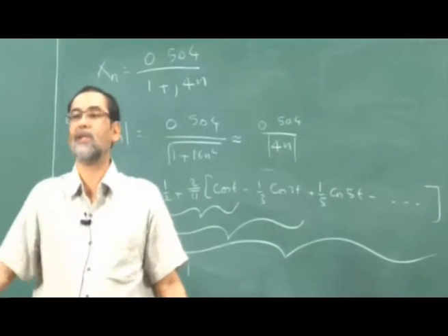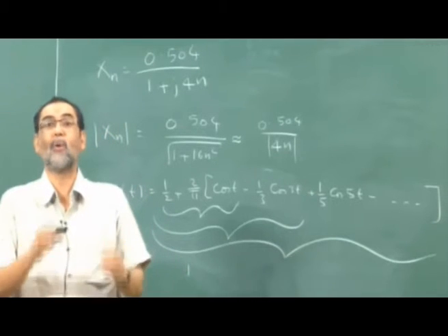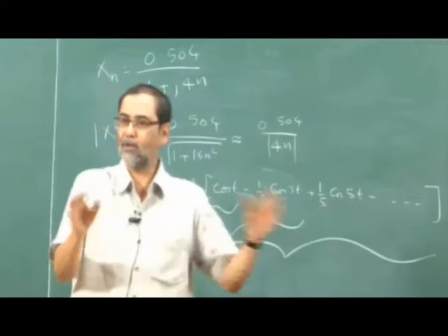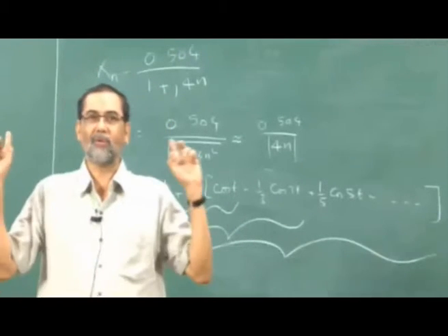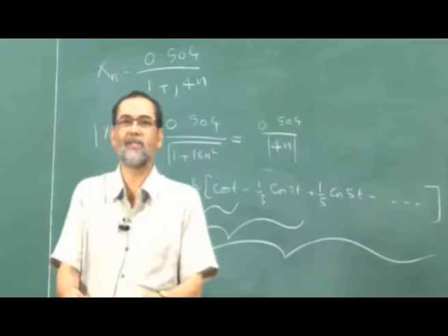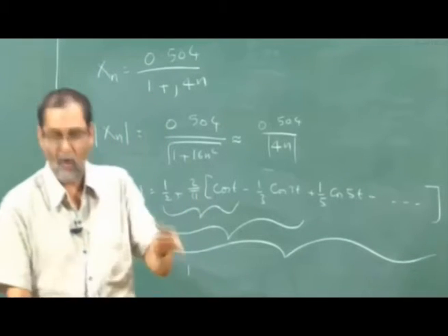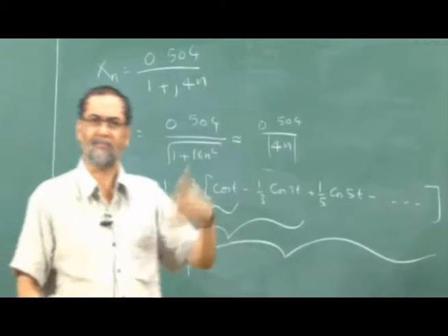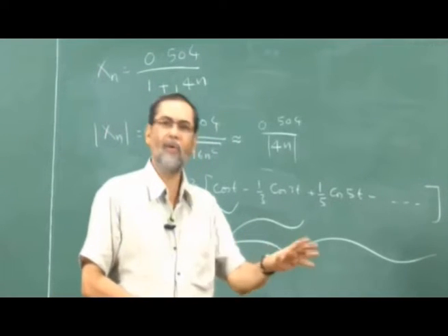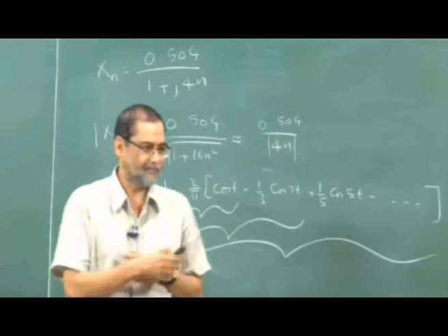That power goes to 0. So they said this convergence is in the mean square sense, not convergence in the mean. Convergence in the mean means both are equal everywhere. So this equivalence the Fourier series talks about for some discontinuous signal is mean square convergence and not the convergence in the mean. So all these ideas took lots of time, 70-80 years after Fourier died. So now we understand that the two might be equal in some sense.